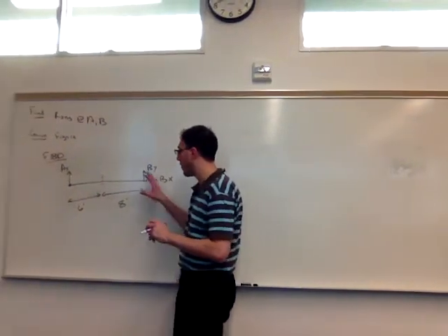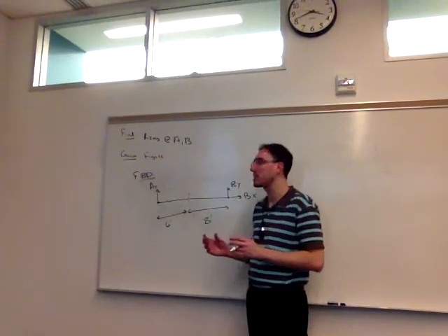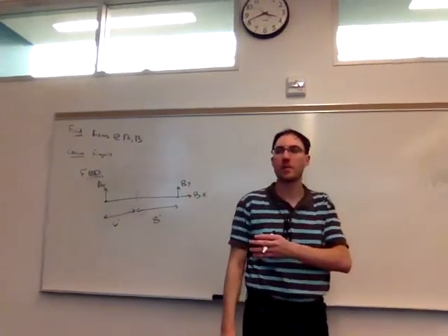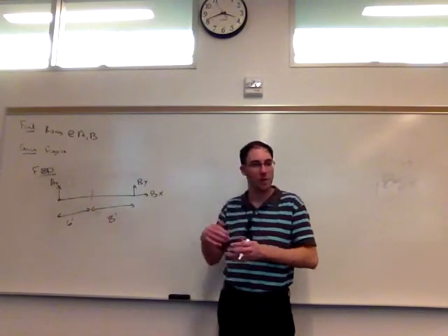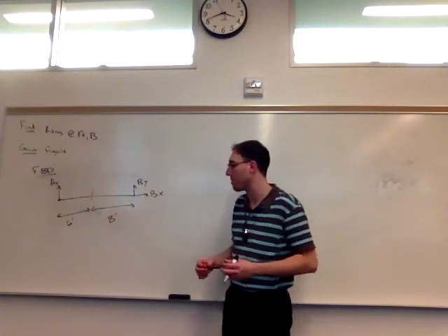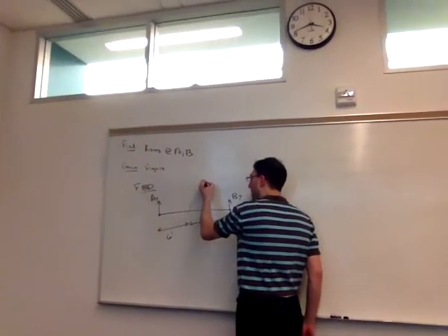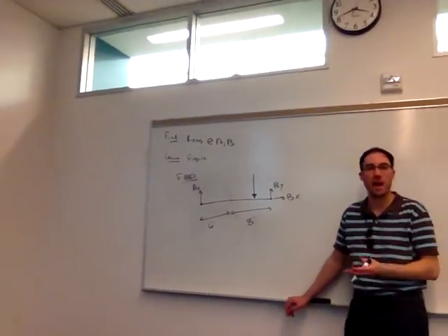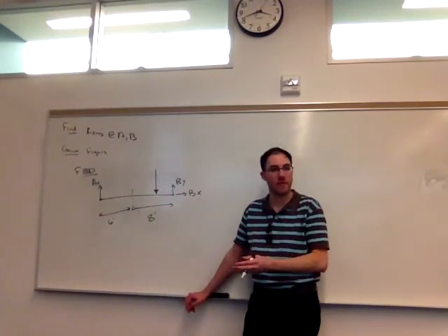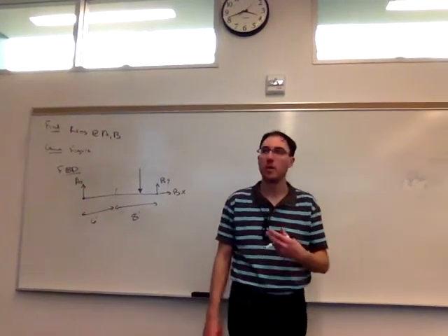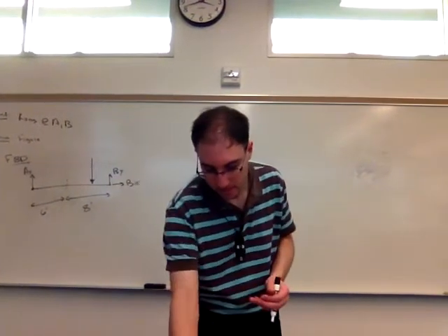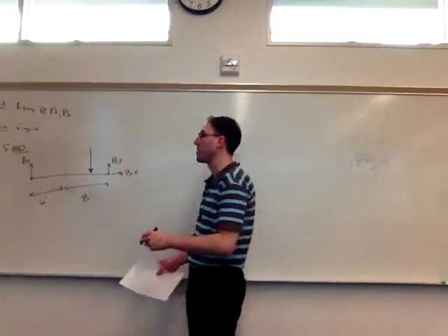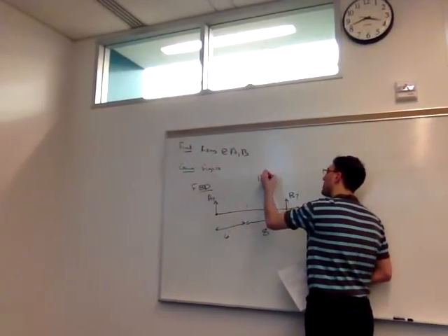Just like we looked at for the solid shapes or the sheets of shapes, the equivalent force of this distributed load from 6 feet to the right of A to B is going to be the area under the shape, or the area of the shape. In this case, the rectangle is going to have an area of its base times its height. So 150 pounds per foot times 8 feet is going to give us a force with its units in pounds. For the rectangle, base times height, we get an equivalent force of 1,200 pounds.